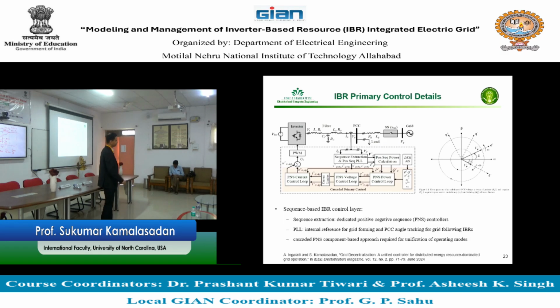So I think one of the interests that you had yesterday, you were asking about, can I have a single phase inverter working as a grid forming architecture? A single phase inverter doesn't have the concept of grid forming architecture, because in order to form the grid, you need to convert into DQ. For that you need A, B and C, and A, B and C is only coming from three phase. If you have one A inverter, another B inverter, how do you get A, B and C?